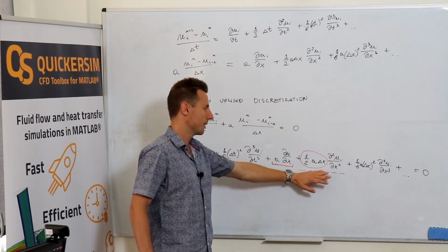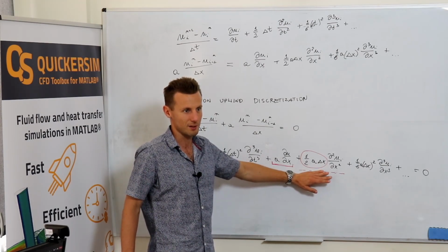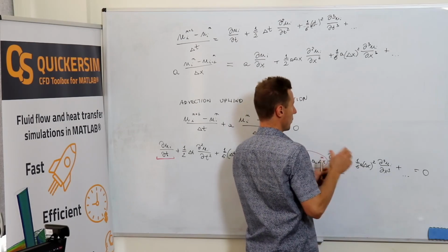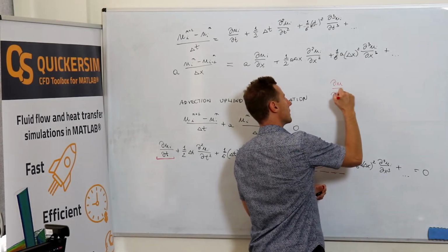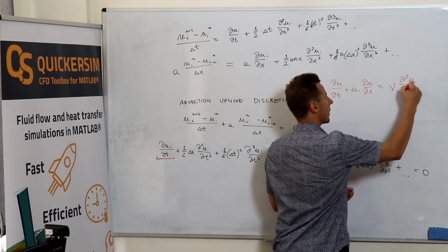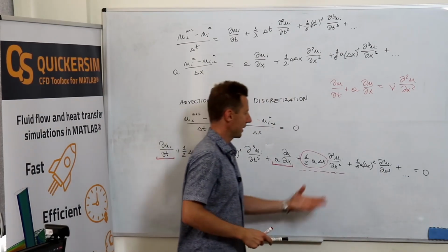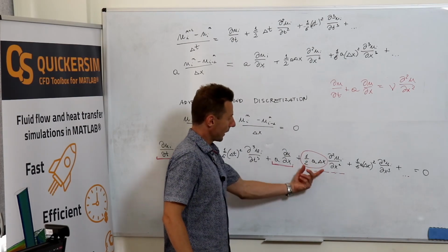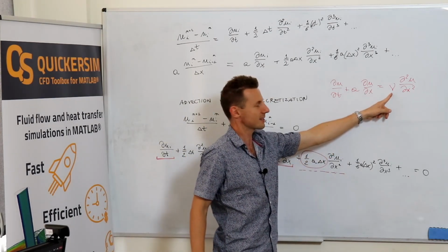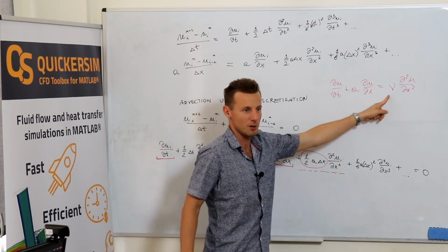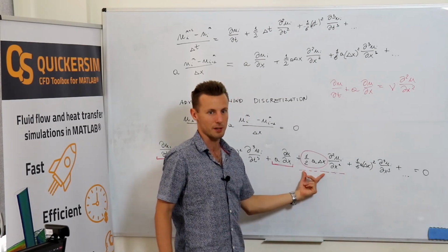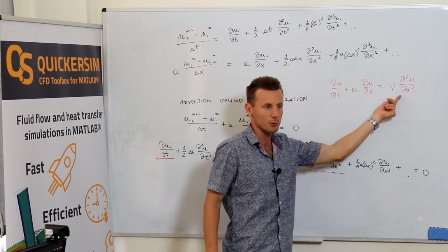And then the argument goes, okay, if we can calculate artificial diffusion, then let's maybe, just if you imagine that we would be solving du dt plus u dx equals some nu, then the very nice argument goes, okay, if we can calculate the artificial diffusion and we want really to solve such an equation, then maybe simply let's subtract something like that from nu, because then we know that this term that is lowered plus that one that arises due to the application of the discretization would be exactly what we want to have.